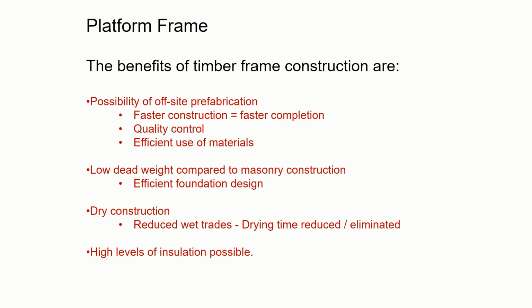Timber frame is a dry construction. We're using lengths of timber, we're nailing them together or bolting them together. There's no mortar to be used. So compared to masonry construction, we have a reduction in wet trades. Wet trades are trades like plasterers, masons, builders who have to use water within mortar or plaster or render, which has a drying time associated to it and has some restrictions regarding the weather.